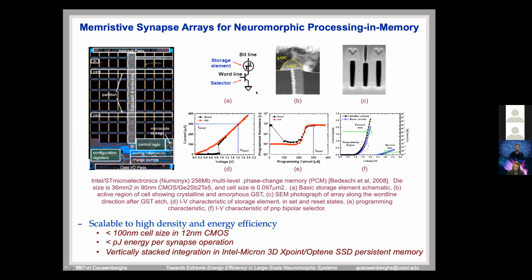As it so happens, there are all these emerging memory technologies, whether it's RRAM for resistive RAM, or here phase change memory, PCRAM, or MRAM, magnetic RAM, or STTRAM, and there are different associations of conductance-based memory arrays, crossbar arrays of memory elements, where the memory is encoded as conductance. You have this word line that activates this conductance onto the bit line, basically as a digital memory. But there's no reason for you to do it that way. You can think of the word line as being a presynaptic action potential that activates your postsynaptic membrane conductance onto the dendrite that you have here, the bit line. So right there you have a biophysical synapse.